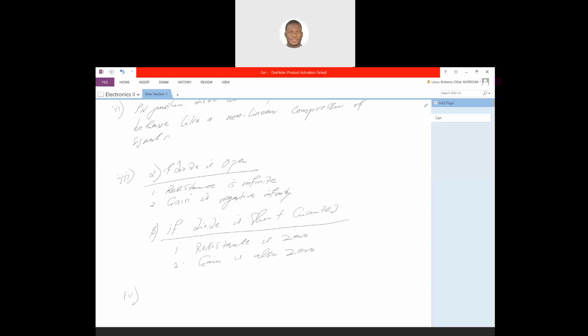So short circuit diodes that are not damaged, in this case, have very low resistance in both forward and reverse directions. So in essence, once you have a multimeter to confirm any of these, if it is short circuit, the likelihood that the diode would burn is very high.